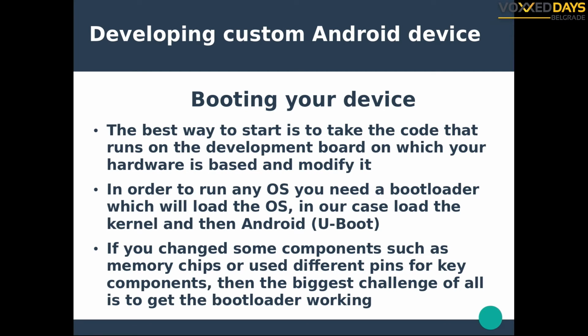I can say that if you resolve that, I'm now speaking just about custom hardware. If you're running on the development board, you will use their example bootloader, kernel, Android. They will supply you with some code to run with the demo images and everything. But if you're making your custom hardware and you got it and you want to start it, I can tell you that probably the most effort that you will invest while doing your project will be to first boot the device.